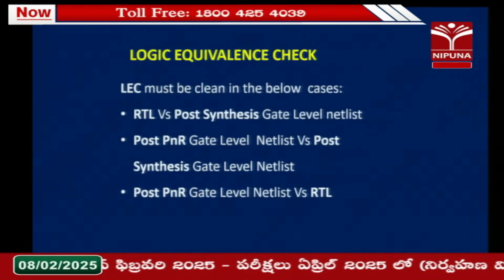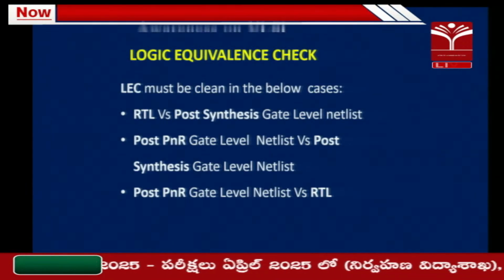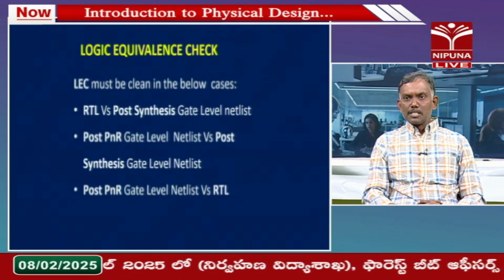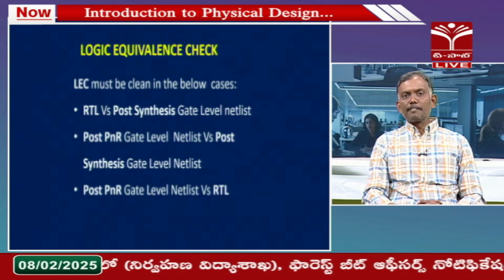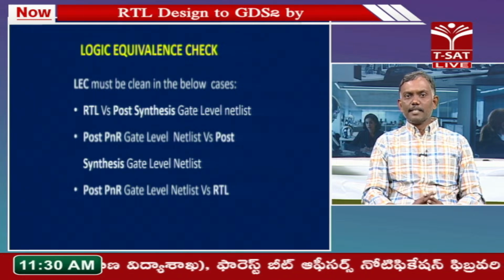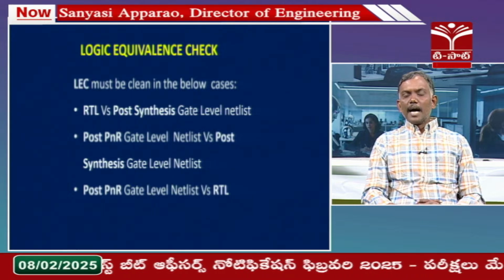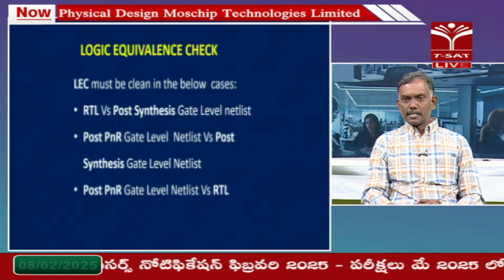Next sign off check is the logic equivalence check. This logic equivalence check is 3 stages. One is RTL versus post synthesis, meaning after synthesis. We already discussed this. We did the logic equivalence check after synthesis, that is RTL versus post synthesis.